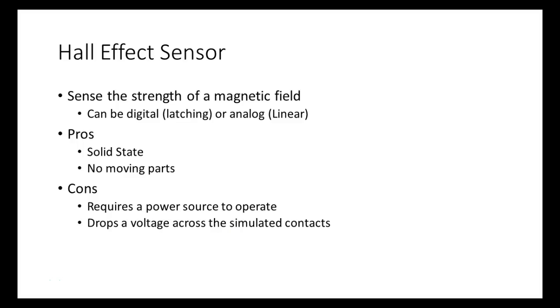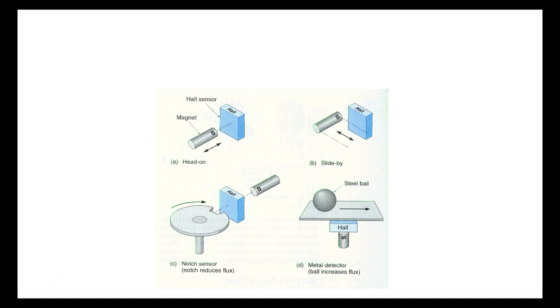And we have 2 types, guys. We have a latching type, which means the way these work is one polarity will latch it. One field pole would latch it, and it would stay activated. I could put it there from now to doomsday. So if a north activates it, I could put a north up there, and its output would switch on, and I could put the north on there forever. What does it take to unlatch it? You have to put a south pole in there.